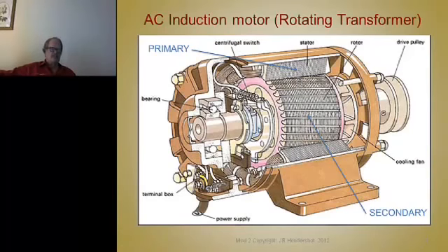This has a centrifugal switch because it's operated with single-phase power, but it's really wound for 2 phases, so it'll start. So it starts as a 2-phase motor, and then when it gets to a certain speed, the starting winding is opened through a centrifugal switch. The circuit's open, so no current flows into the start winding, and it just runs very inefficiently with only 1 winding.